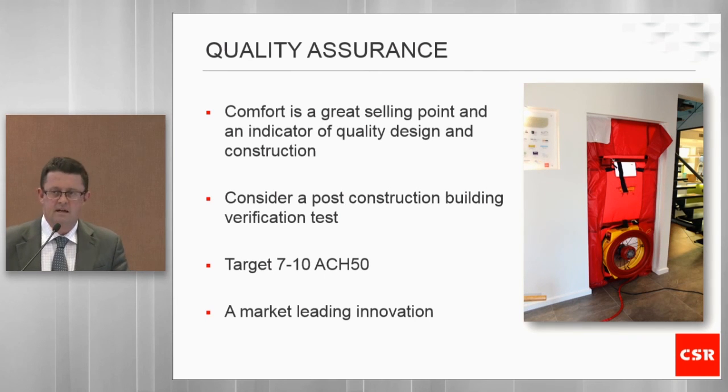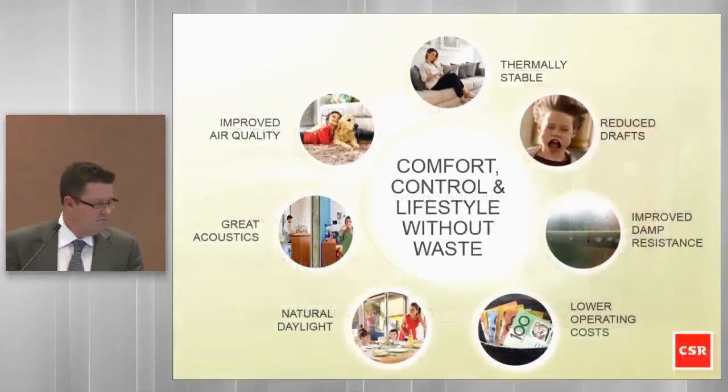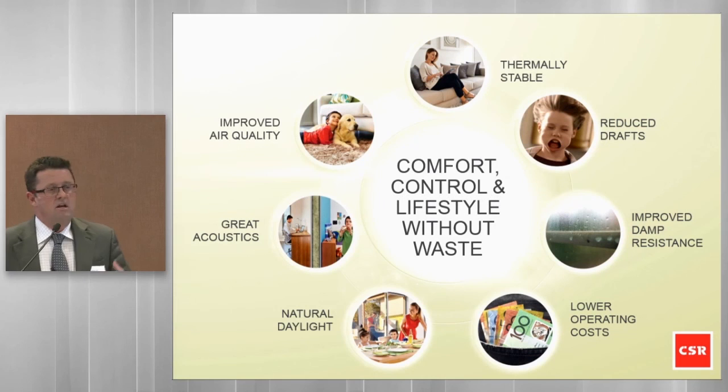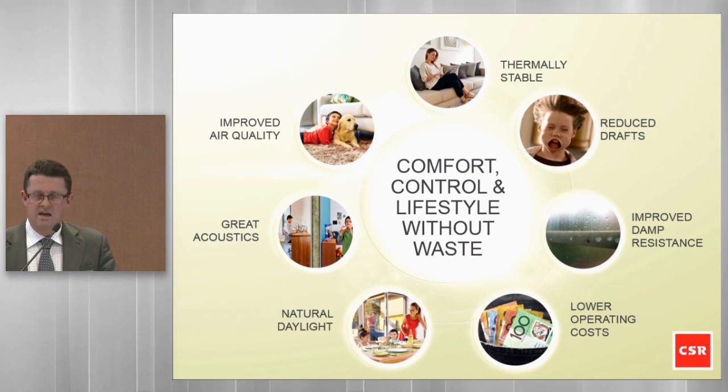Look at that ACH 50, that target figure of between 7 and 10. And from our point of view, we believe that this is a market-leading innovation, very simple to achieve, very cost-effective, and leads to better quality buildings. So again, we know better comfort is going to come with better control. Control ventilation. Let us only have ventilation when we open windows and turn on a mechanical ventilation system. And if we do that, we can achieve a better quality of lifestyle without significant waste.